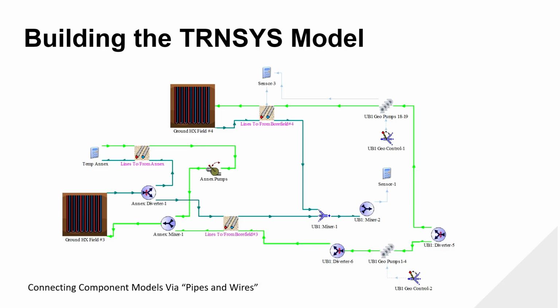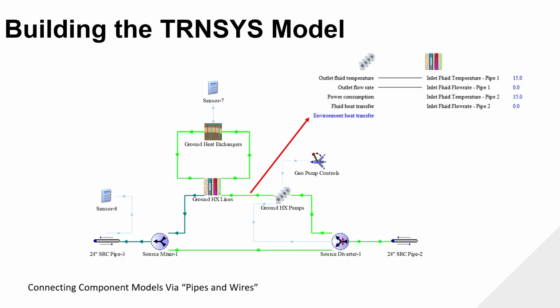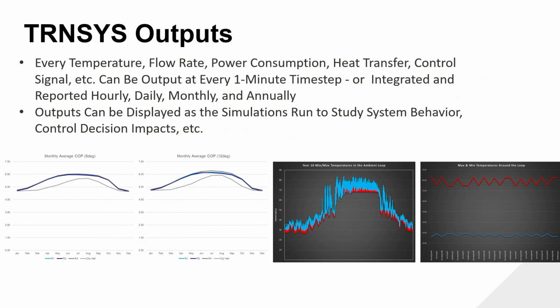Right? And we need to model that. And that's one of the beautiful designs inherently about thermal energy networks and having distributed resources. You have them spread out so they have more land in order to get energy or put energy in. And so they don't get impacted as much as if I had a campus with 600 bores all on one field. That's a much different design. And there's a different thermodynamics happening within the ground in that scenario than if I had 50 bores in 10 different locations. So that's what this really does for you on that level in modeling, which, again, is dynamic.